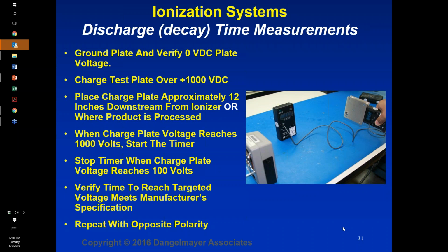There's no mention of the size of this isolated conductor, and quite frankly, a small wire that's charged to 35 volts is going to be much less of a hazard than a large metal plate charged to 35 volts. So that whole idea of 35 volts needs a lot more discussion. Ionizers are probably not going to be the source of the problem.